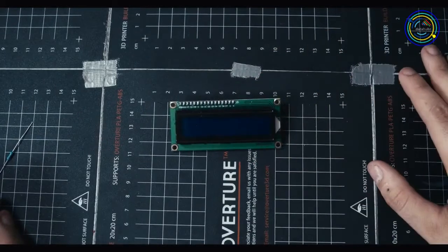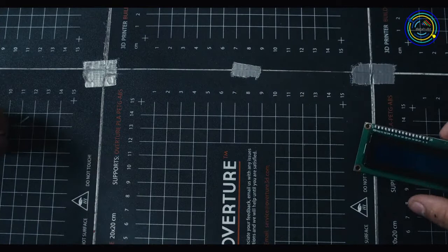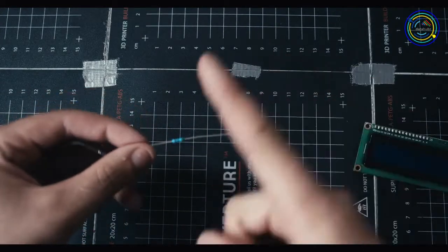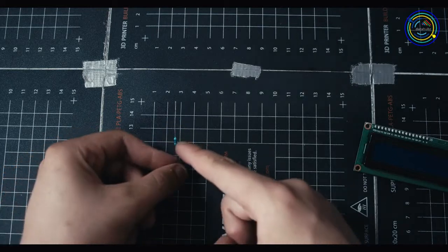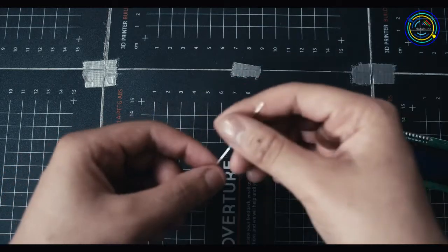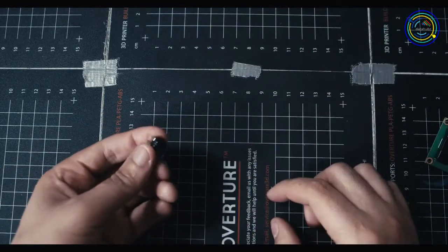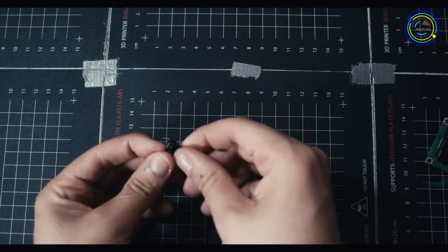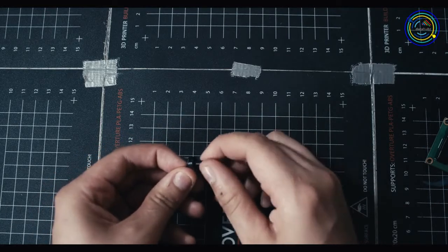So what you're going to need for this build is an actual character display. You're going to need a 220 ohm resistor that looks like this. I'll put up the colors on the screen. Usually you just have to match the colors that are on this little blue piece that's out of focus, and you'll know which one's the 220 ohm resistor. You're going to need a potentiometer, which is pretty much a screw knob. It says on it 10K, which is the one we're going to be using. This is going to be to change the brightness of the screen.